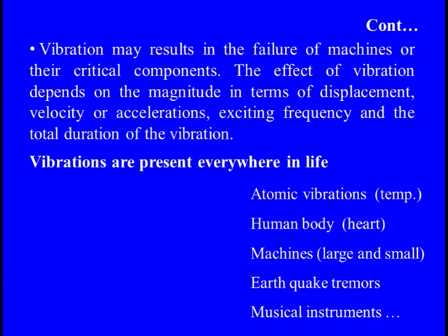Since the amplitude of either the displacement, velocity or acceleration clearly reflects the vibration significance, we can find out at what frequency this amplitude is there and what the duration of the vibration is, that means for how much time this frequency is present and this much amplitude is coming out from the system. So if you want to characterize the vibration, there are two main features: one is the exciting frequency and one is the amplitude